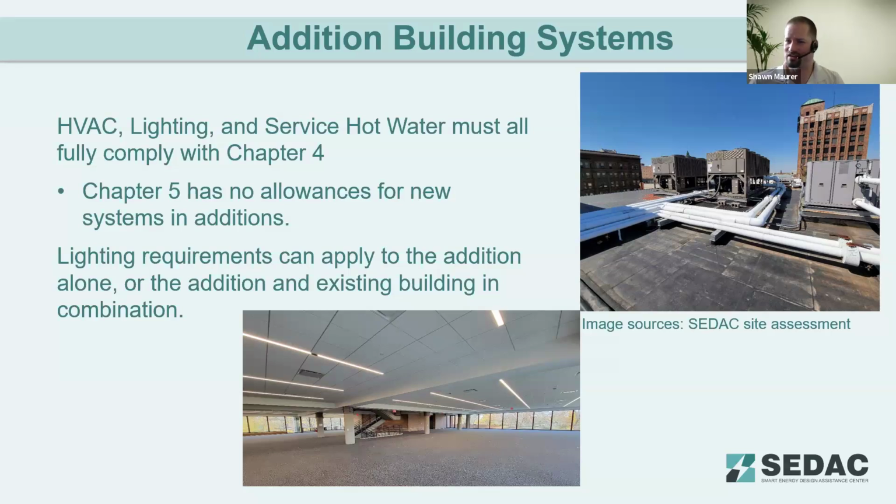But as far as HVAC and service hot water, again, as we noted earlier, generally if you're making an addition to the building, if you had a well-designed HVAC system or service hot water system, they should have been sized for the existing building's loads. The addition would push beyond those loads. So they should either have their own systems or the existing systems updated to handle the additional loads for the addition.